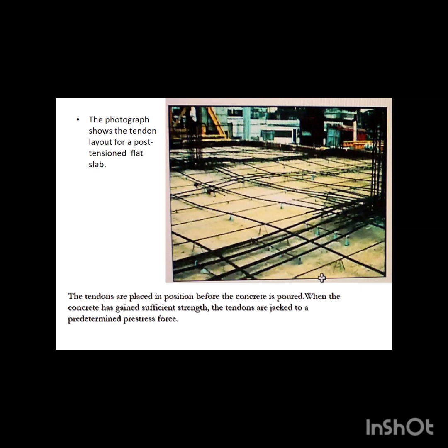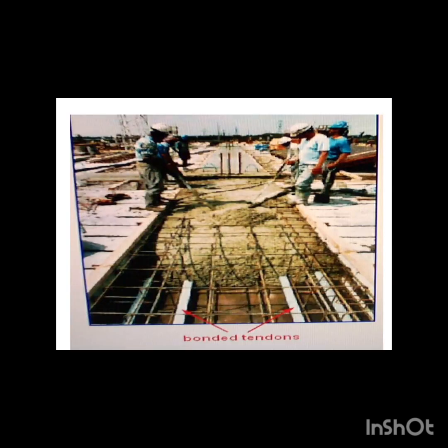This photograph shows the tendon layout of the post-tensioned flat slab. The tendons are placed in position before the concrete is poured. When the concrete has gained sufficient strength, the tendons are jacked to a predetermined pre-stressed force. Bonded tendons. We can see that these are the bonded tendons.